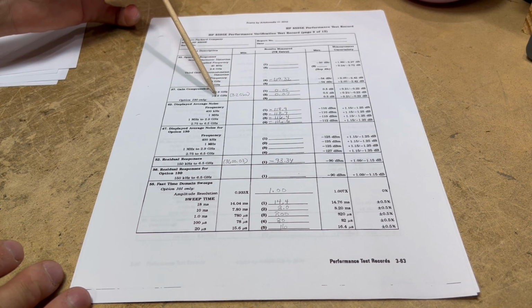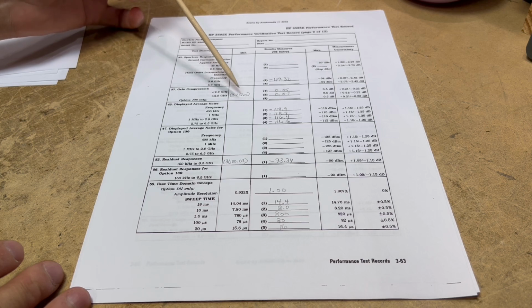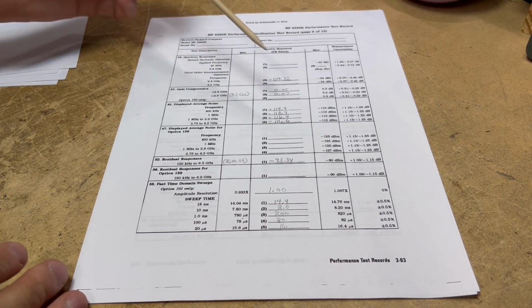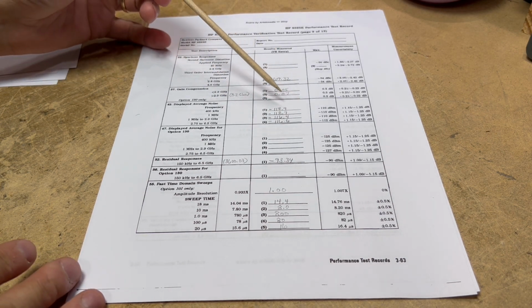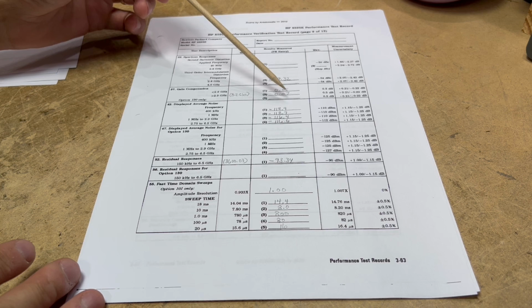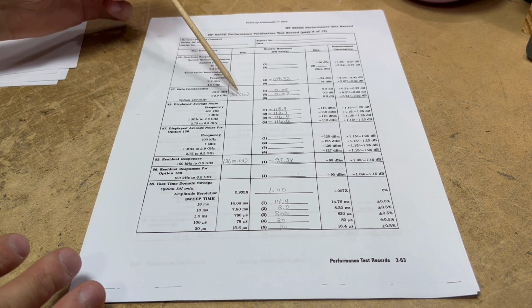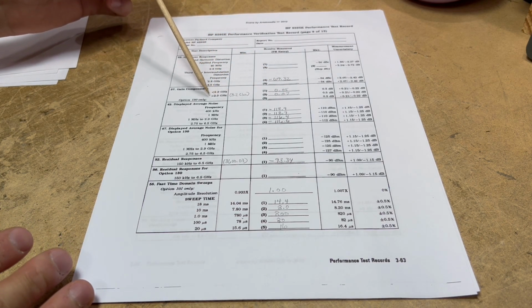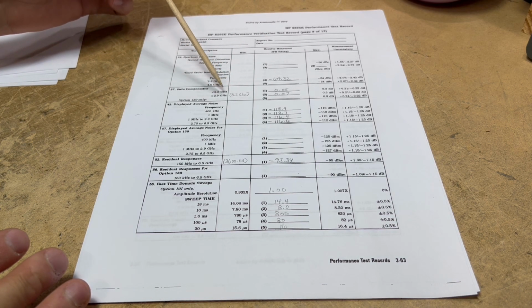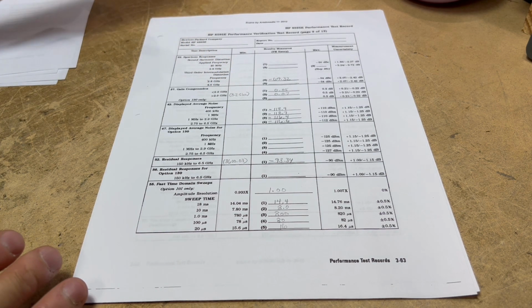for the greater than 2.9 gigahertz. I took it to 3.2 gigahertz because I could use the 8646C, and I could use the 8672A. Those two units, the 8646C with a maximum frequency of 3.2 gigahertz. So I was able to perform that measurement at a slightly lower frequency. I think the test wanted to do it at 4 gigahertz. So I was able to measure both bands there with a little modification.